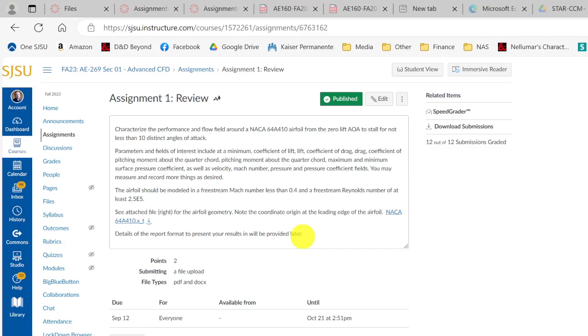Got it, because that's the focus mainly. So because you get really large gradients right up here. You do still get gradients back here, but less severe. Okay. So if you have a choice of getting the boundary layer prism layer to agree, and you can only get it to fit really well in one spot, get it to fit where you have the highest gradients, which we expect near the leading edge of an airfoil.